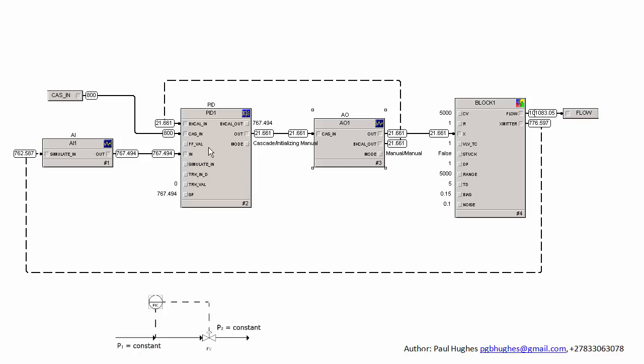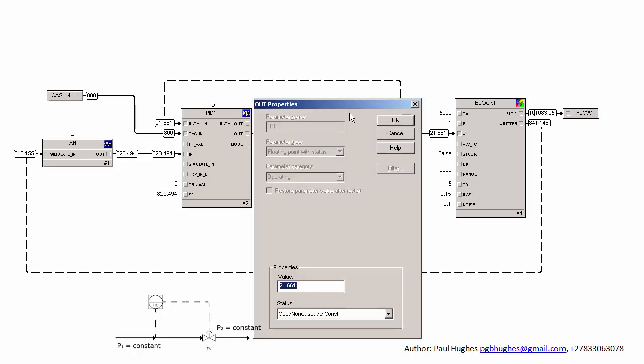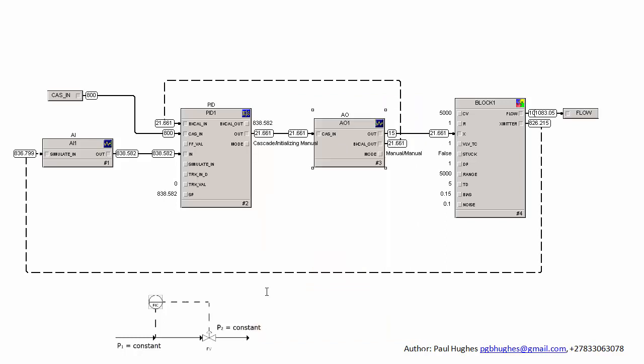In other words, it tells the master loop that the output channel is no longer participating, and I can adjust the output value and say I want the output to be 20% or 15% only. This information gets fed back to the master loop to tell its output to track it. This is how the initializing gets done.